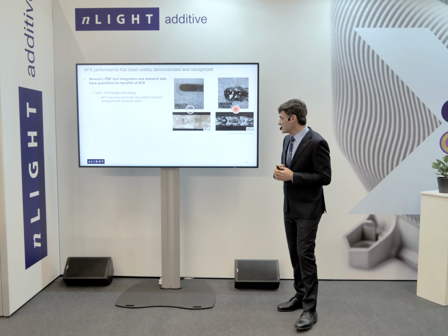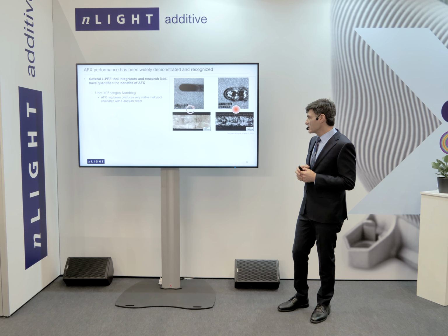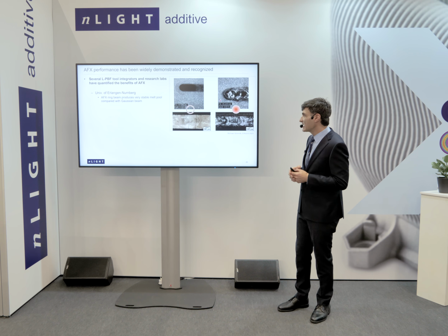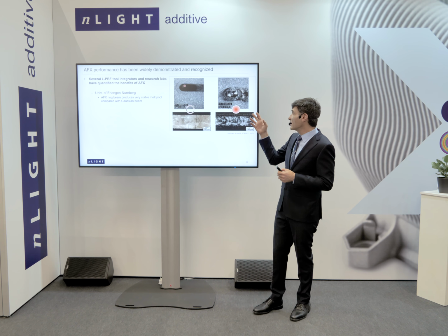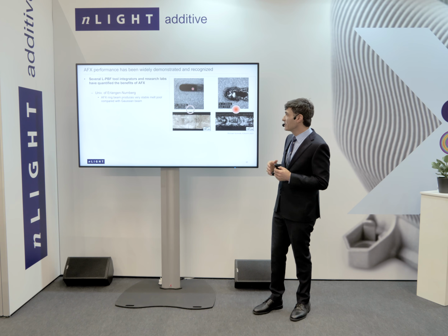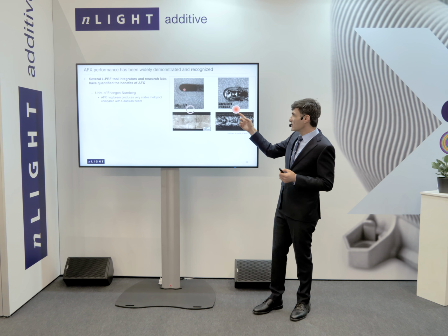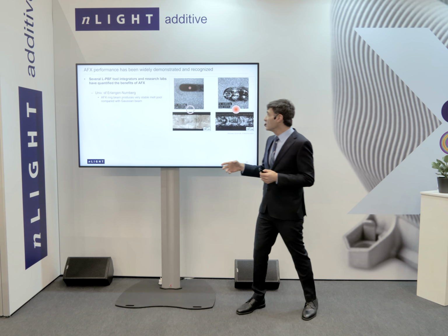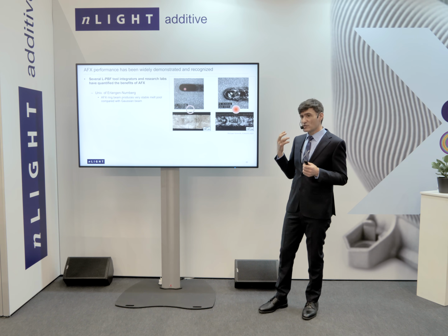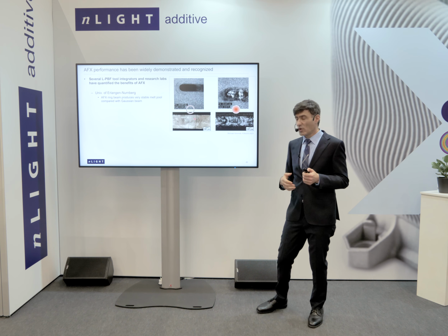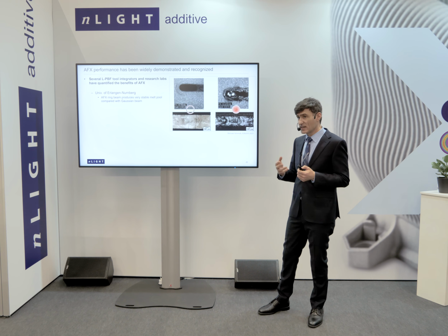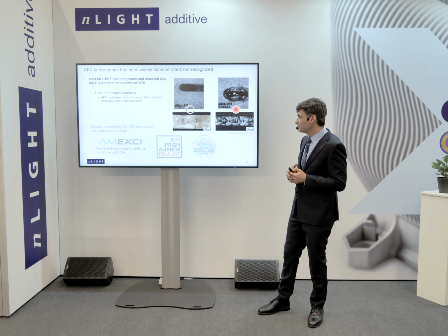Last, this is a screen capture from a talk that Michael Schmidt gave at iCALEO. He's from the University of Erlangen-Nuremberg, and he's comparing with high-speed video the melt pool dynamics from a standard Gaussian beam and the ring beam. And you can just see visually how much more stable the melt pool is, which of course leads to better material quality, fewer pores, and other imperfections.